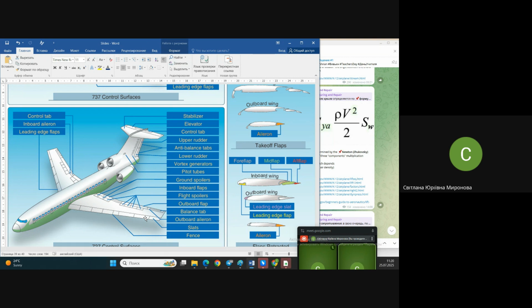So aileron, flap: how to distinguish them in the real structure mechanically? Usually it's visible that they are different mechanically when you watch them on the wing or from under the wing. And of course, when they are working, you will not mix them up at all. Once again, ailerons work like scissors, one up, another down. And flaps go only down, depending on landing and takeoff, to different values, different angles.